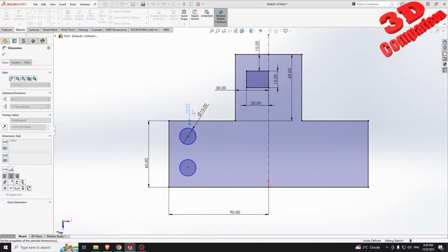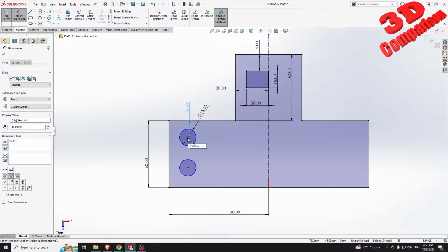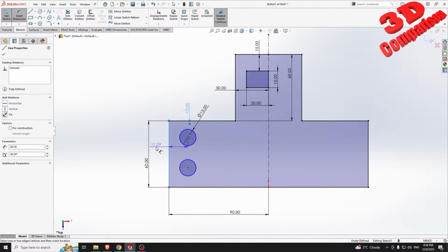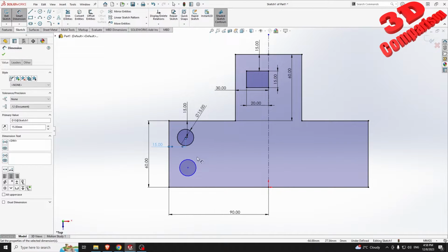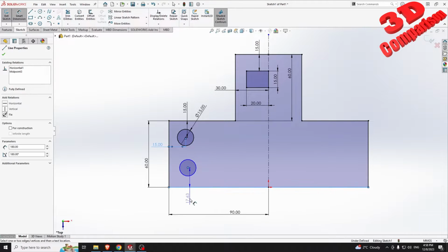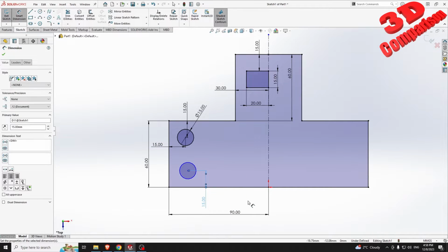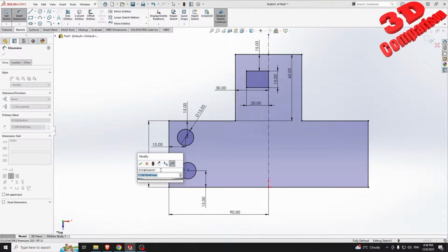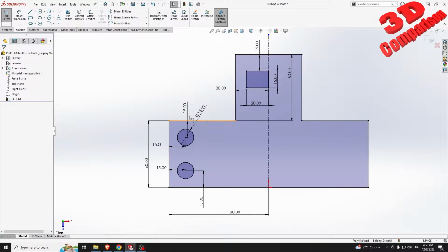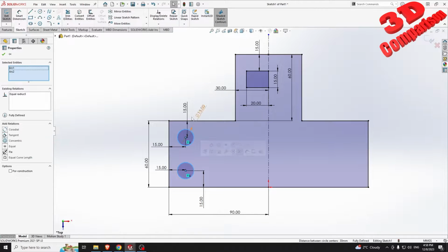And I'm also gonna position those circles to be at 50 millimeters from the edges. So in this case, we're gonna have that distance added. I could have made use of another symmetry to position this over here on the bottom, but I will just roughly position like this. Not roughly, with those exact parameters of 15 millimeters.